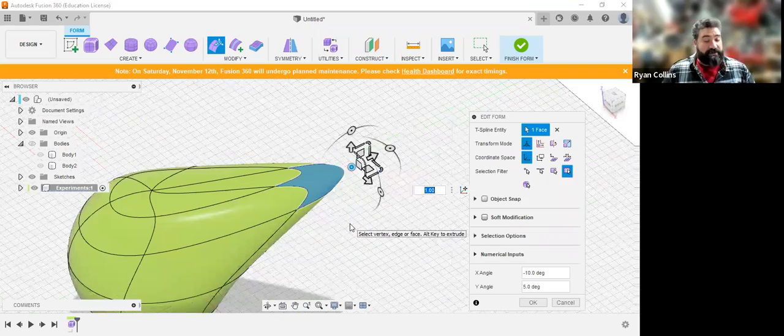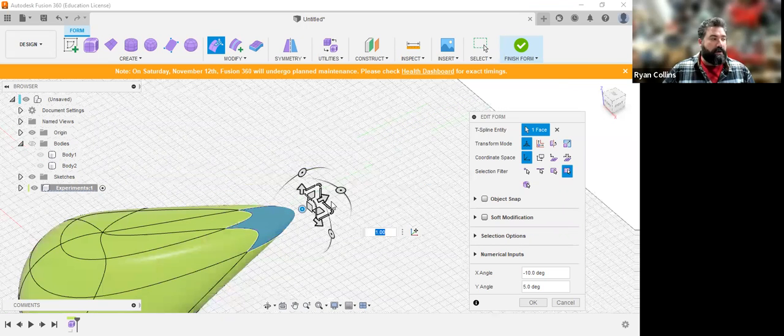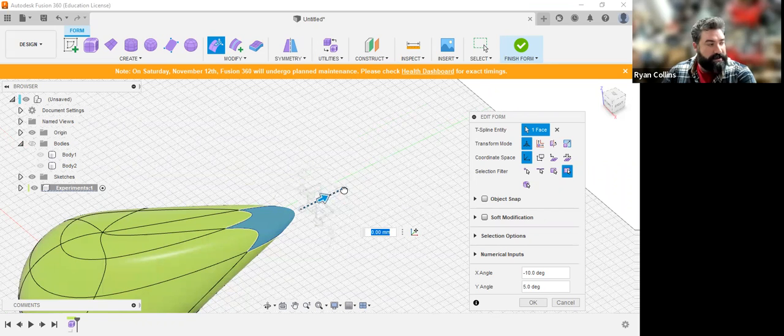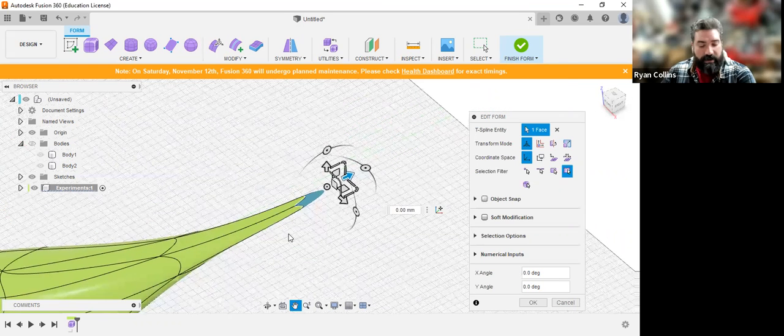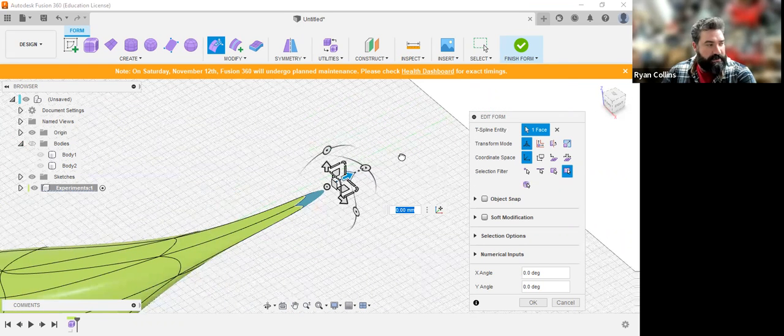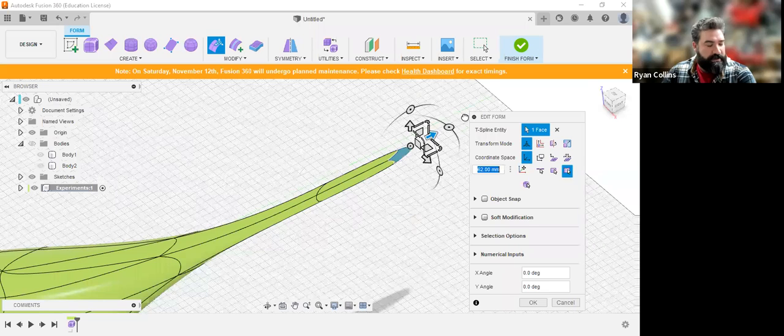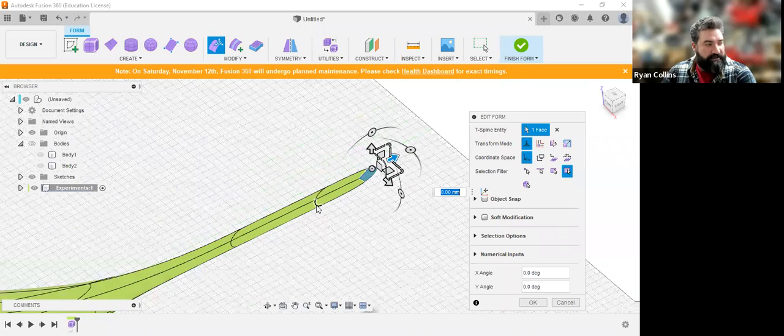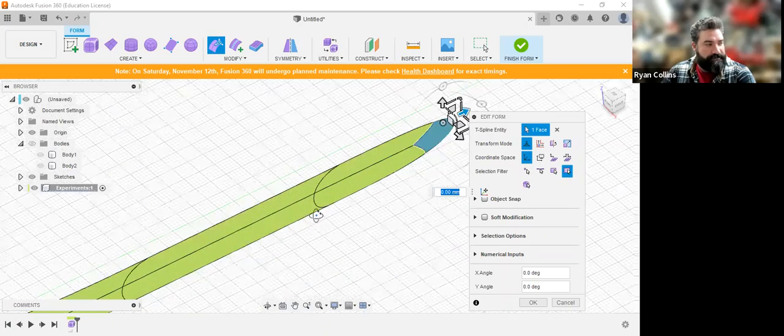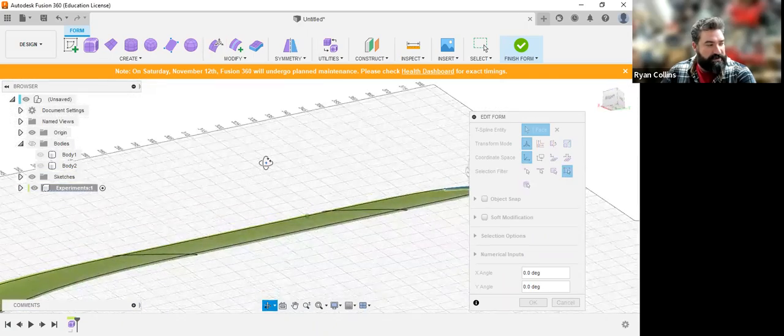Now, some of the other tools that you can work with on the fly are hotkeys. You can press and hold Alt, or if you are on Mac, Command, and you can free extrude a face. So I currently have Alt pressed, grab that, and you can see what just happened. I'm no longer pulling just a face, it added one. Release Alt, press again, and you can keep doing that. Between each one, it's inserting a face, it's inserting a line, and it is creating an extrusion.